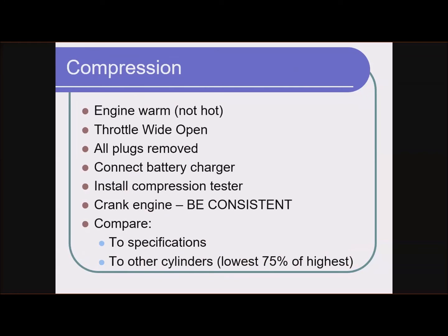We remove all of the spark plugs. I'm not going to say that I've never done just a single cylinder. If I knew that a particular cylinder was misfiring and I just wanted a quick check to see if the problem was compression related, I've done it. Just pop a plug out, screw the gauge in, crank it over, see if I'm at zero on that cylinder or close to it.